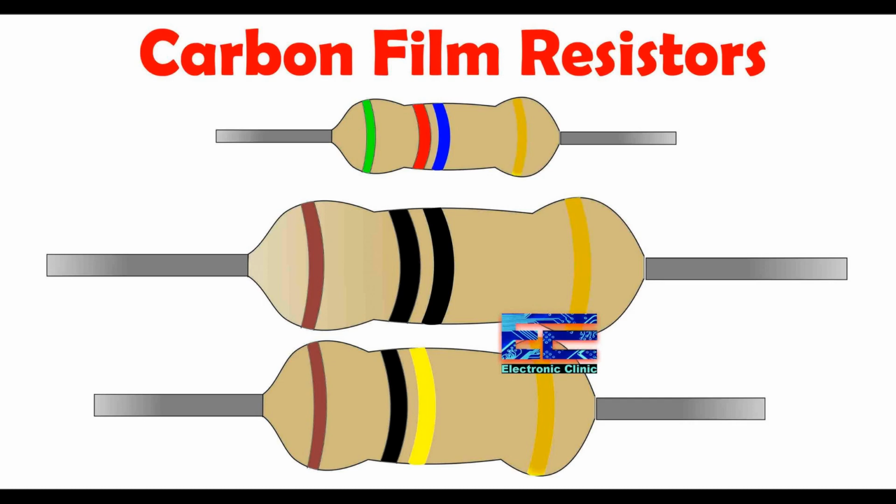Stable resistors are less susceptible to moisture-induced drift. Load stability: the stability of a resistor's resistance value should not be significantly affected by variations in the applied voltage or current. In other words, the resistor's resistance should remain consistent under different operating conditions.